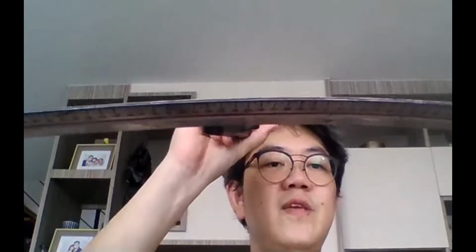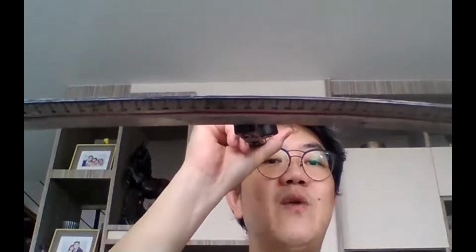If I can just hold one web like this, now when we look from top view, you don't see the webs anymore. When the buckling occurs, from top view you see the member move out of its own plane. There is no help from your diagonal or vertical webs. That is why, when you consider this, the only help you may get for your chord will be the braces from the purlins or from the extra truss you put in the system. Does that help? Better than not trying, right?